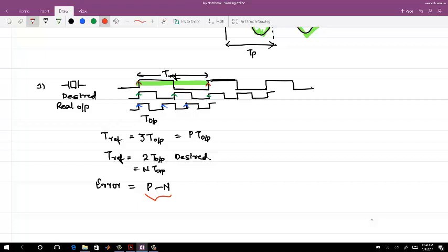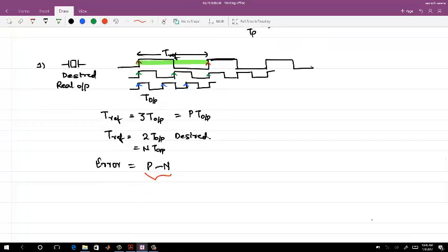So if I was counting only one cycle, then I say, okay, I need to increase my frequency, I need to reduce my cap. So the thing is, you see that there is a reference which is coming from the oscillator. There is an LC oscillator which I have designed. I want the frequency to be twice. I observe something and I say, okay, if this number is greater, I need to increase the cap. If this number is lesser, I need to reduce the cap, right? And I have to do it in a closed loop fashion.